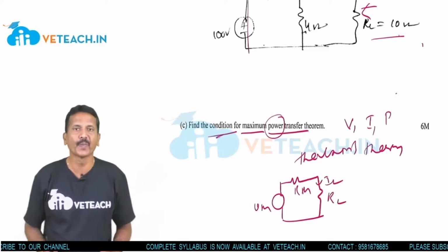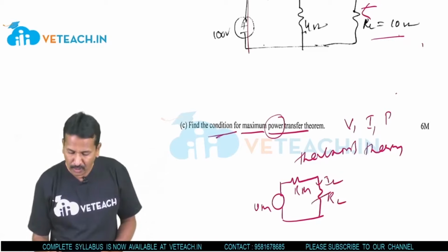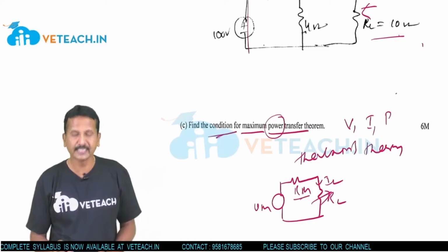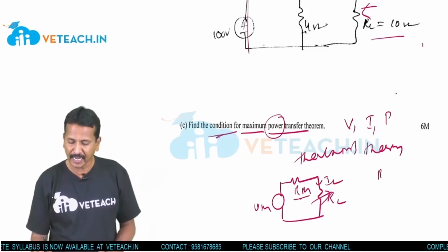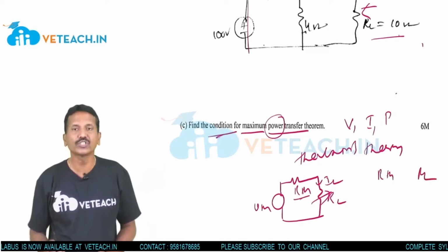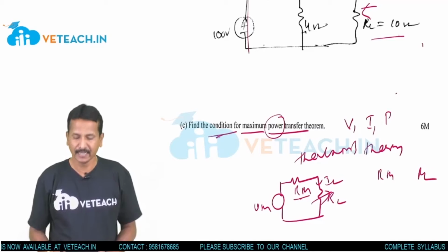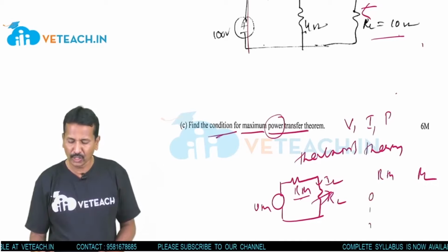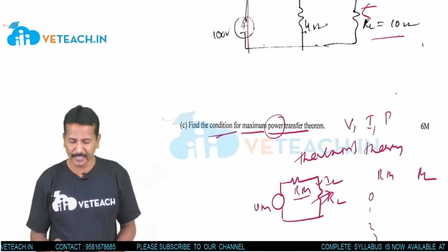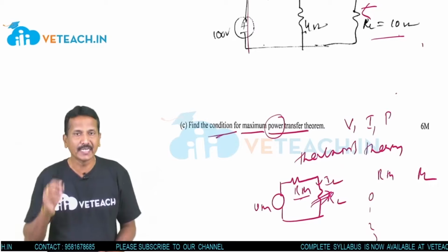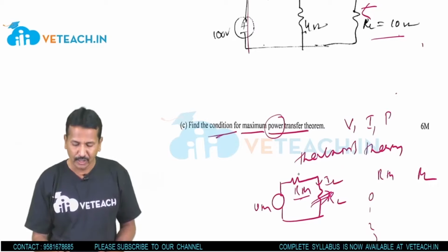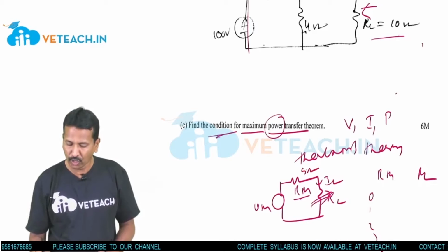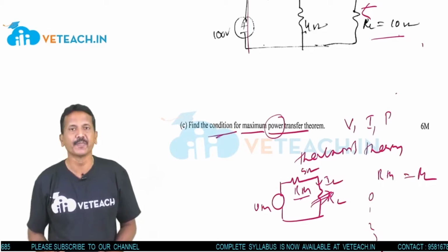Okay, students? Now, this is a variable value. Load resistance here is variable. RTH is a fixed value. RTH and RL both are resistance only. Both are resistance. So power transfer is going on well. From 0 to 1, 2, 3 like that, the value of RL goes on increasing. But at a certain point, suppose it is 5 ohms, example 5 ohms, at 5 ohms these two values are same.